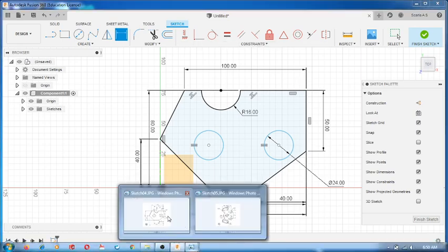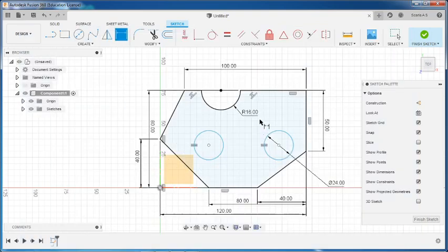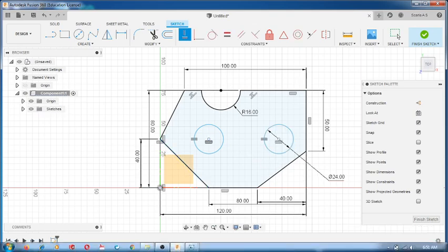Then we have to give the Y position, horizontal and vertical. If it is aligned in the same way, the dimension is not defined separately, so we will take it as 40, so that it is passing through the 40 line here. We can use horizontal vertical on this point. Similarly this center and this center also horizontal vertical.